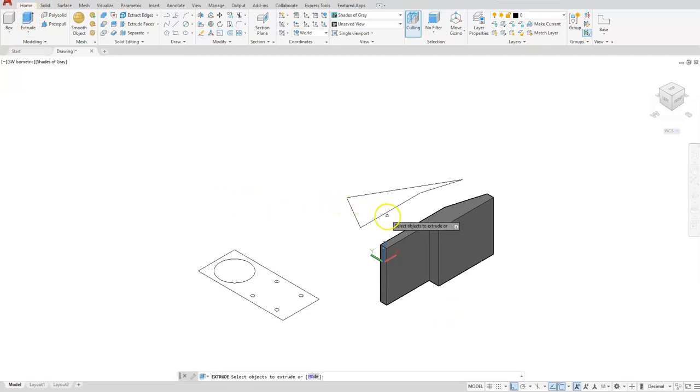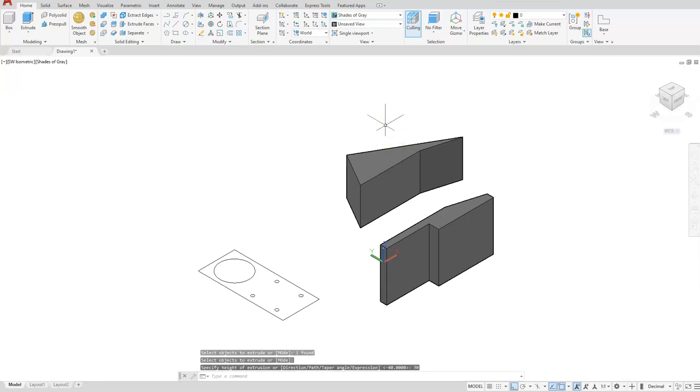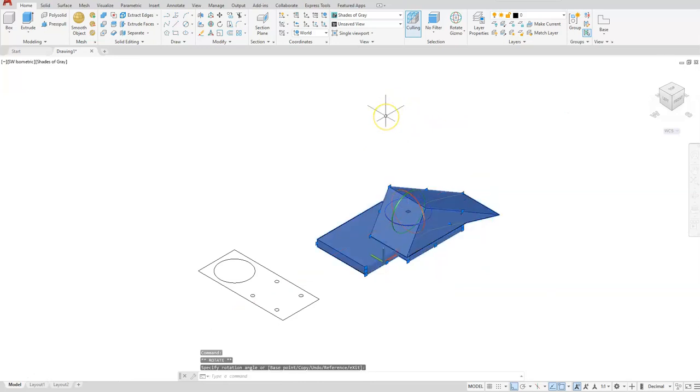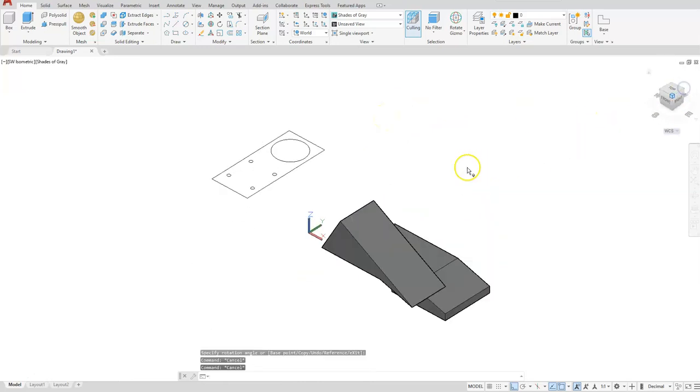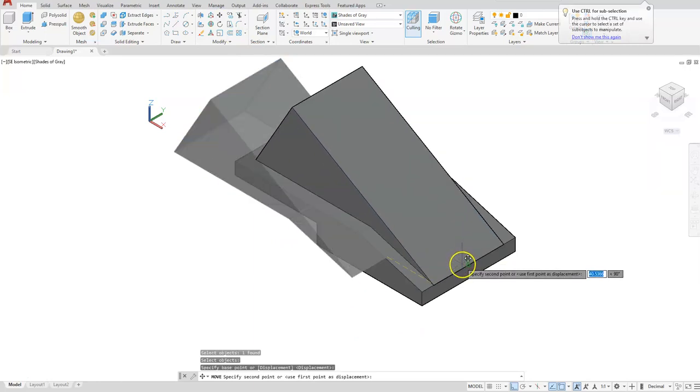And let's go ahead and extrude this top shape. A distance of 30. I'll stand both of these up. So I'll go to the rotate gizmo. Select both of these, the red axis, and I'll stand them up like so. I'll move this one from this midpoint down to that midpoint. So let's move this object, this midpoint down to this midpoint.